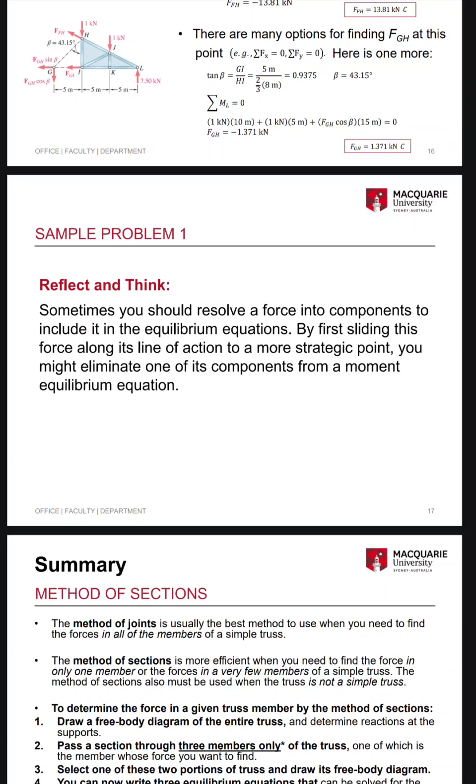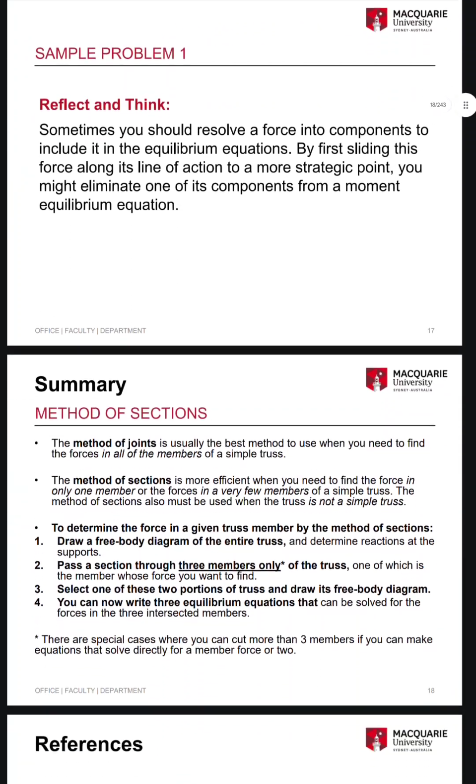Reflect and think. Sometimes you should resolve a force into components to include it in the equilibrium equation. By first sliding this force along its line of action to a more strategic point, you might eliminate one of its components from a moment equilibrium equation.